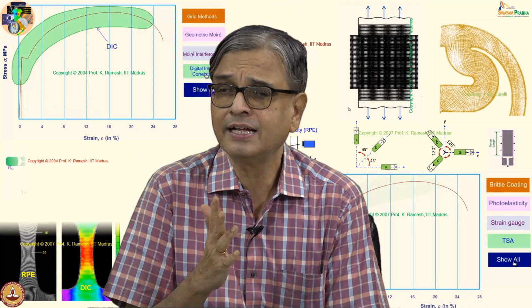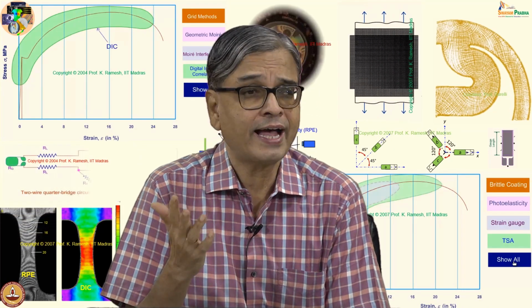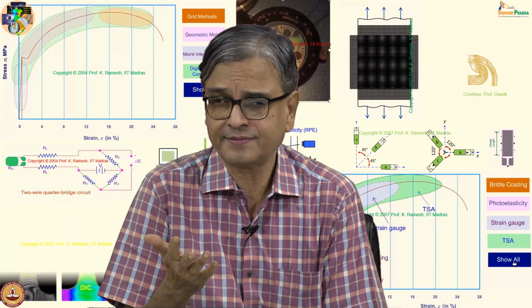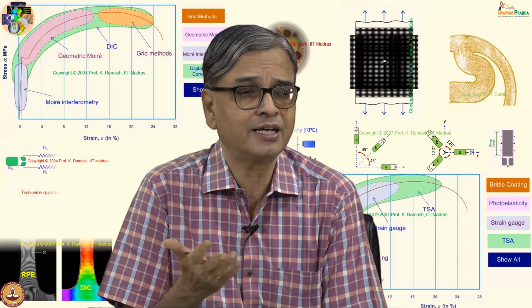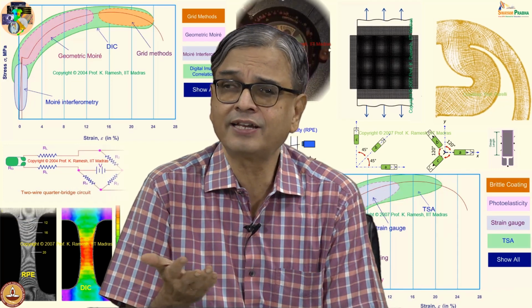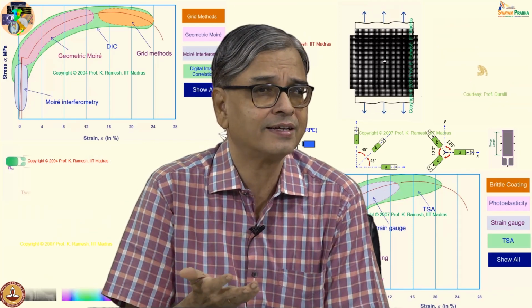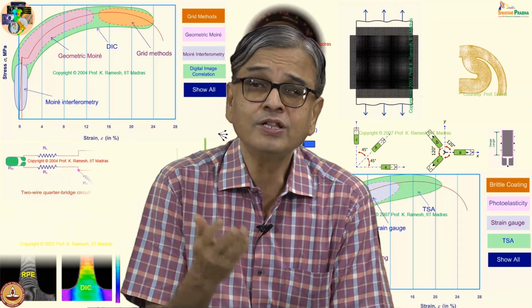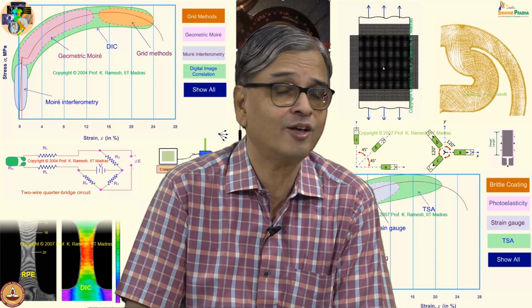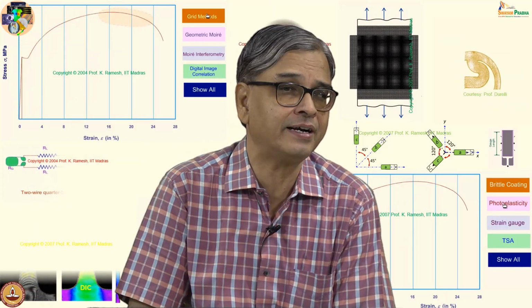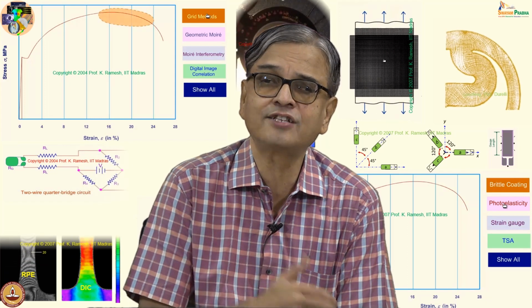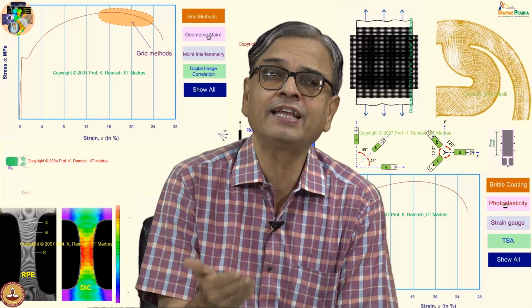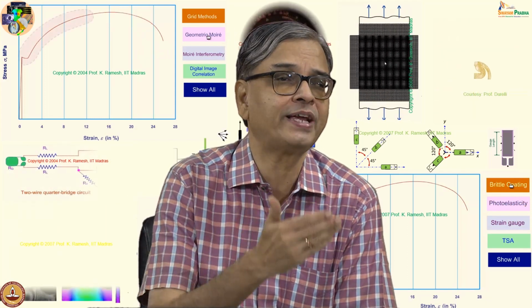I have also said you have load cells, even a vegetable vendor these days has an electronic balance. Am I right? How do these electronic balances operate? They all have a strain sensing element, which is basically a transducer where you have a strain gauge pasted on an appropriate spring element.